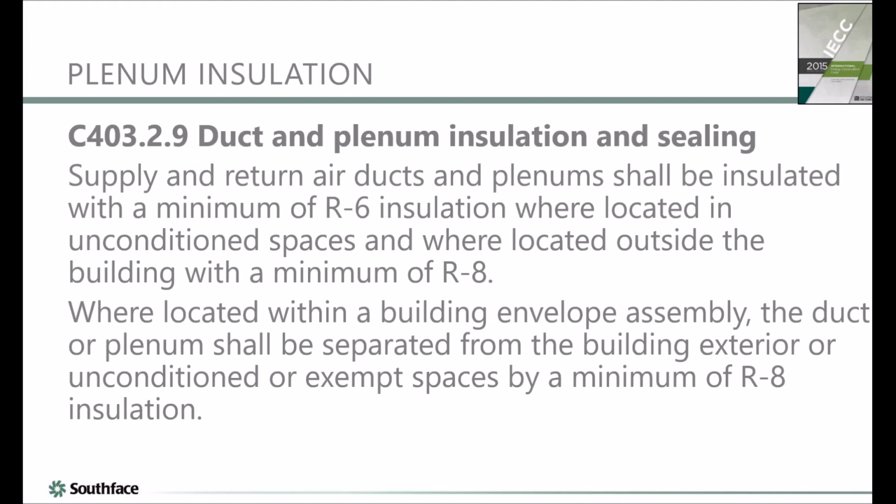And actually, ironically enough, if you take pretty inexpensive construction, steel stud, 16-inch on center, 2x4, and somebody puts an R13 batt in there, that effectively is only an R6. So you're not even meeting that capability. And it's another concern. I don't know that that's the major issue. I think it's really more about leakage, but R value is a factor.